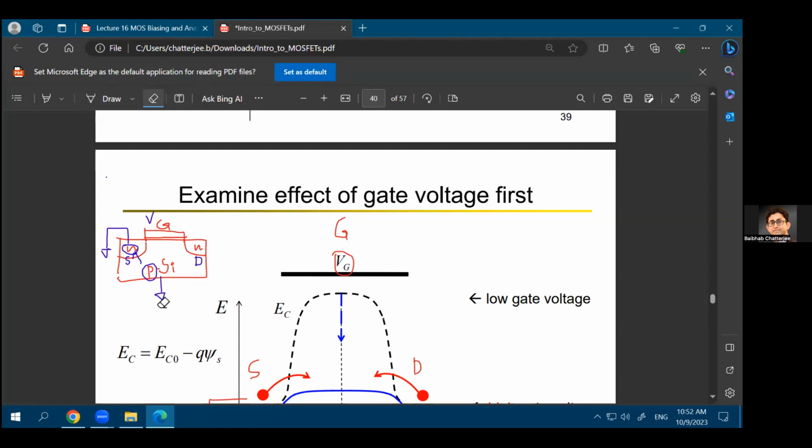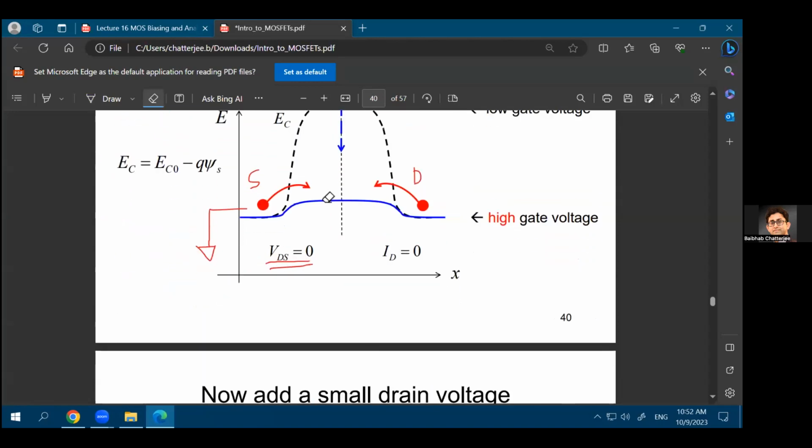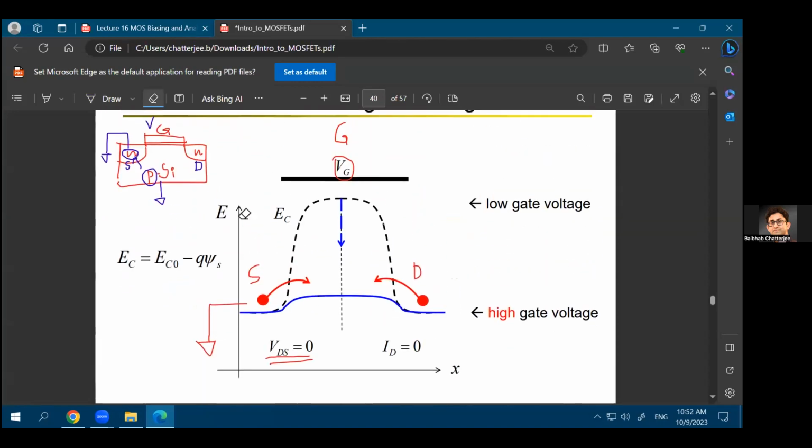Similarly, for a P-channel MOSFET, you'll connect the body to the highest voltage in the circuit, which will be your VDD. So for a P-channel MOSFET, you'll always connect the body to VDD. For an N-channel MOSFET, you'll always connect the body to the ground. That's a very important thing to remember, because without that, none of your circuits during your labs or in your simulations will work. Okay. So this is without applying any kind of gate to source voltage.